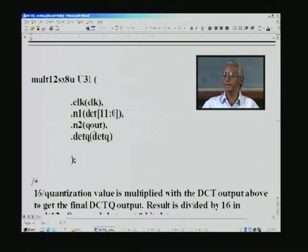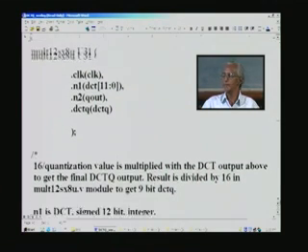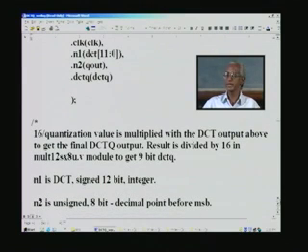Now, from this it should be apparent what we are doing here: from one module we are connecting to another module, and inside that module it will have the very same name, and because we are making a physical connection like a wire or a net, it is called a wire. You have a Q out here, which is the ROM quantization table, and finally out comes the DCT queue here, and this also has 8 pipeline stages. Overall pipeline stages, if you remember, in the architecture we have seen to be 45, and when we see the actual waveforms we will understand this very clearly.